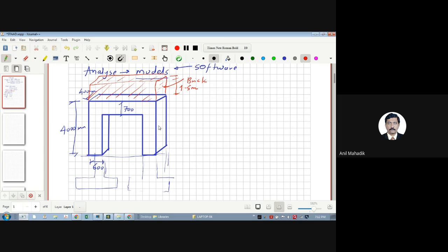as far as structural engineering is concerned, the structure has loads, and due to the loads there will be stresses, and to resist the stresses we are going to put material into it. It may be concrete, steel, or whatever. And to control the deflection, we will decide the sizes of the members like beams and columns. So we are more concerned with the loads coming on the structure and its geometry also.